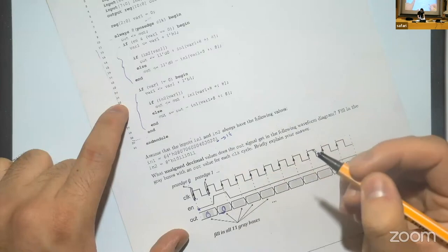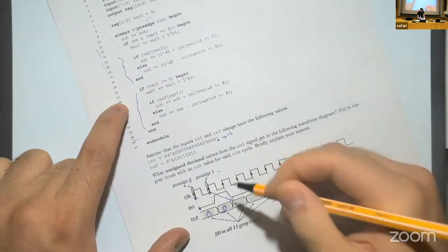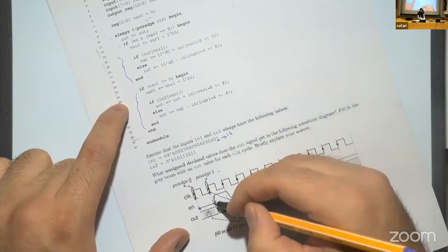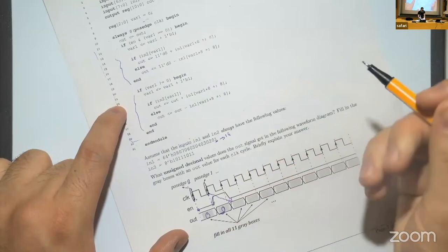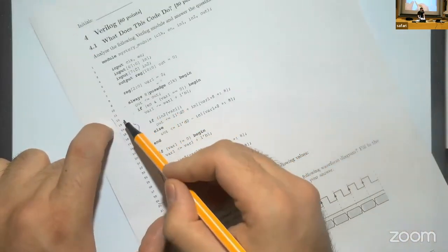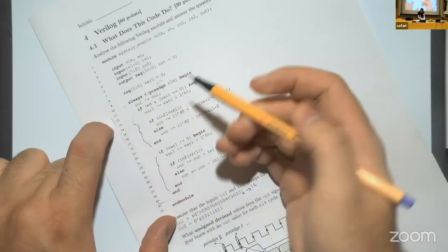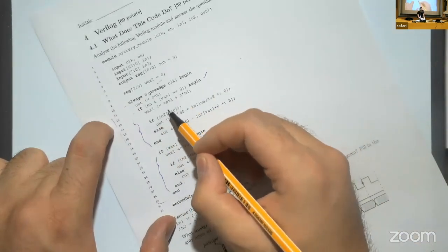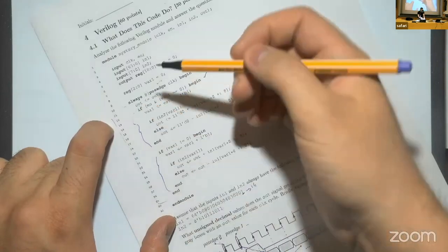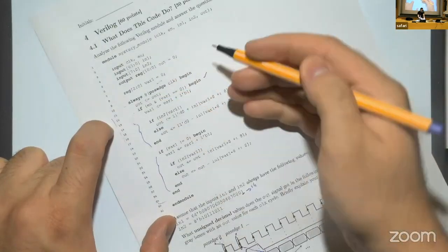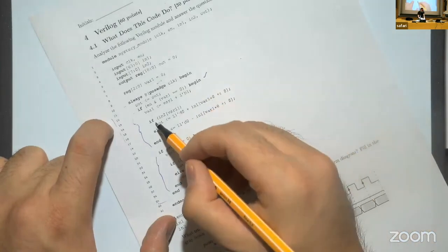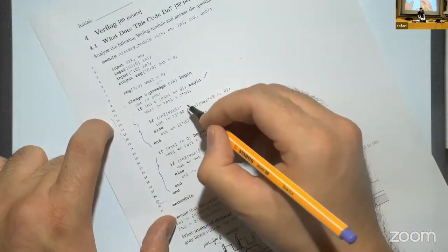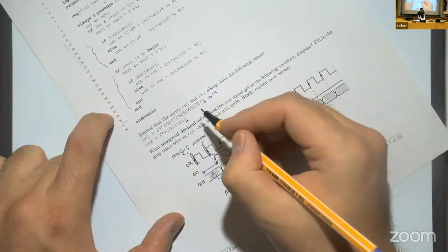So this posedge clock 1 will affect this one. Here we see that enable has risen. That means that enable becomes 1. Now that means that this if clause, which is on the 12th line, will be satisfied. But variable 1 becomes 1 only after the always block has executed, so now it's still 0. So here we go into this if block with variable 1, which means we check the 0th bit. We check this 0th bit, it is 1.